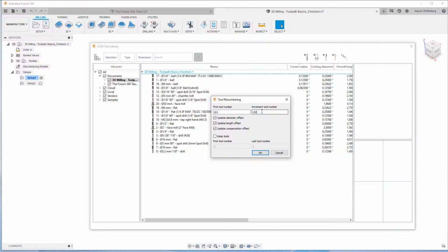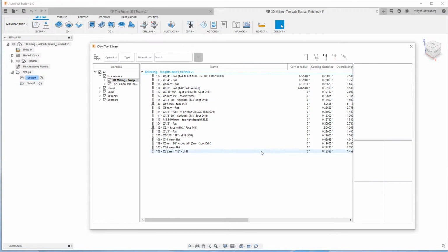You can make it 151. In this case, I would say increment those by 1, however many tools there were. And I can have for the first number being head 1, and I'd have tool number 1. So if I renumber them, now I have tools that I know are going to be in head 1 for the first digit was 1.